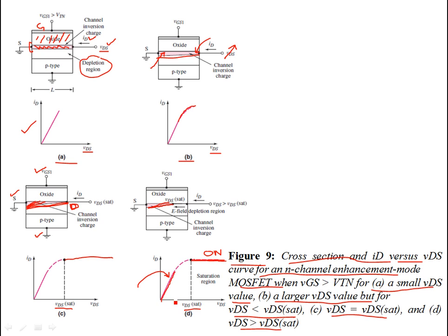This is for a particular VGS. So this is the linear region of operation, where the transistor is used as an amplifier. And if the gate source voltage is less than the threshold, the transistor is off over here. So you can use the transistor in saturation and in the cutoff region as a switch. It is either on or off, depending on your gate source voltage. And in this region, it's a linear amplifier. So in this region, you can use the transistor for amplification purposes.